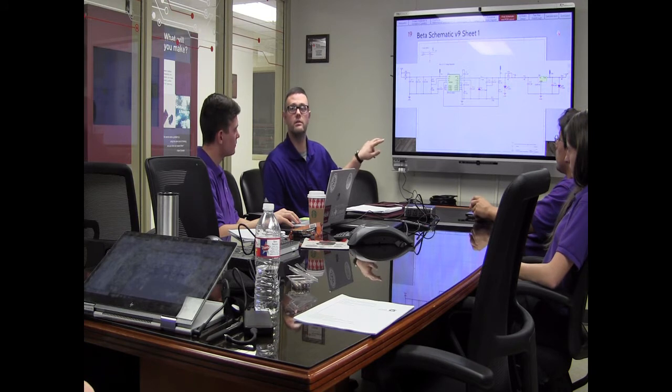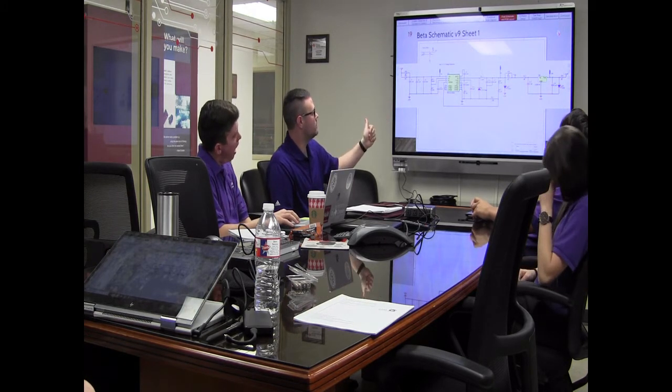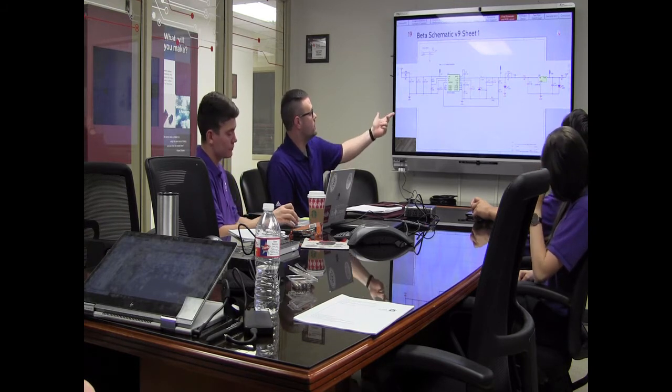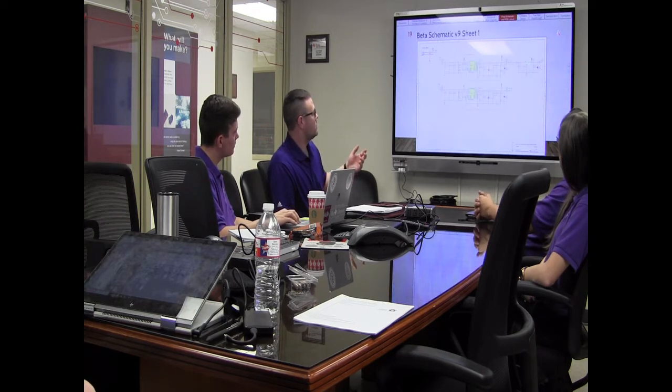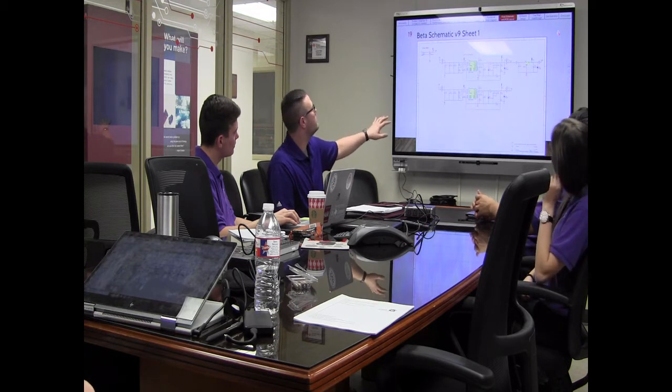They're picked out specifically because they have internal resistors. In an earlier version of the design, we had external resistors, and with lower part count, we went to the one-piece version. So both of those do 0 ohms between them, and then we've got a simple 3.3. We take that 5 volts down to 3.3 for our CC3200, and then that goes onto our board. And then there's a second exact copy of the 12 volts to 5.5 volts just below it.